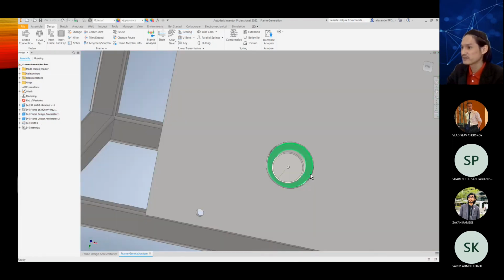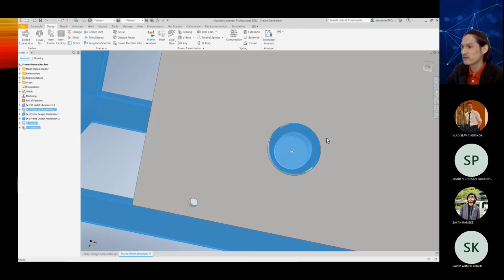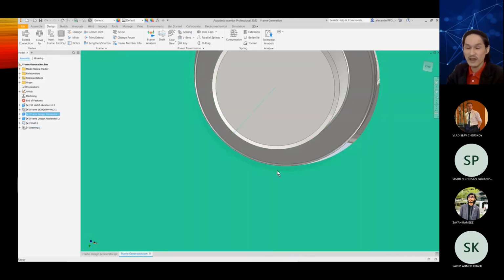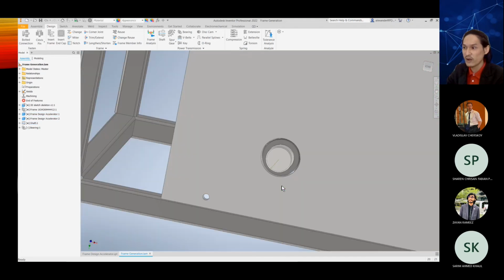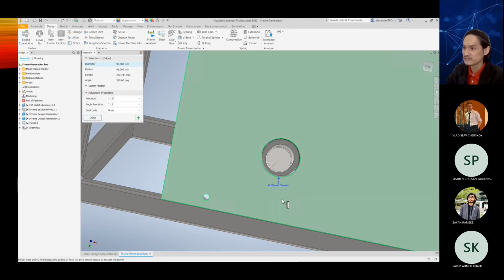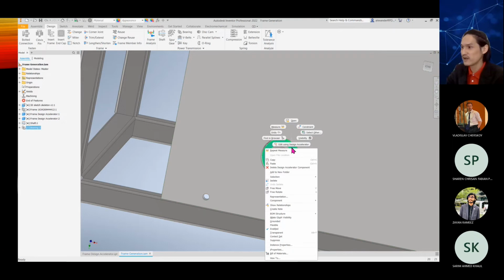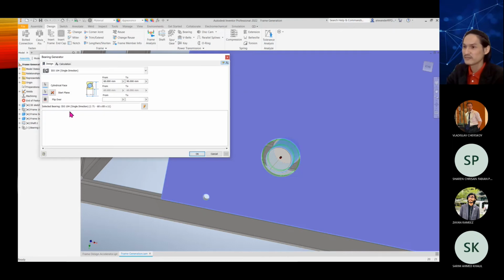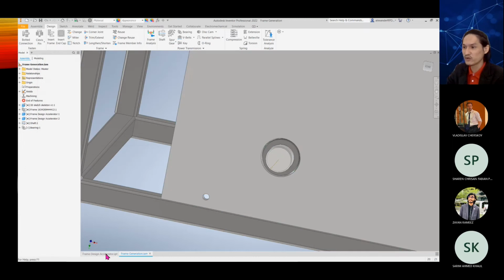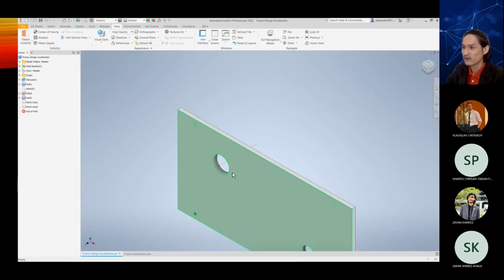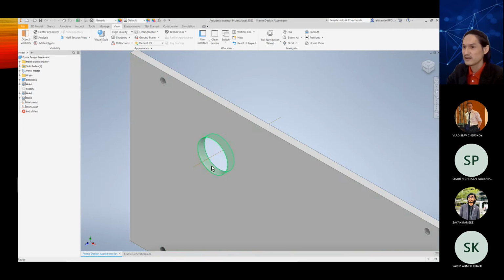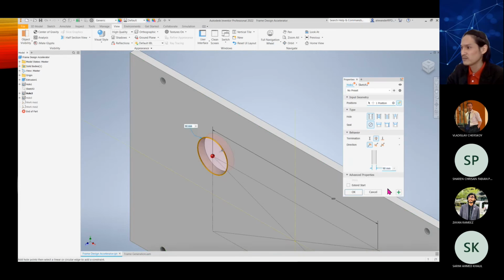Now they generate a bearing for me. But this bearing is 85. Under ISO, they don't have 90. So what I can do, because I know that this hole is 90 and this bearing is 85, is I have to go and change my design. I have to go back to here, and this hole, I'm going to change it to become 85.